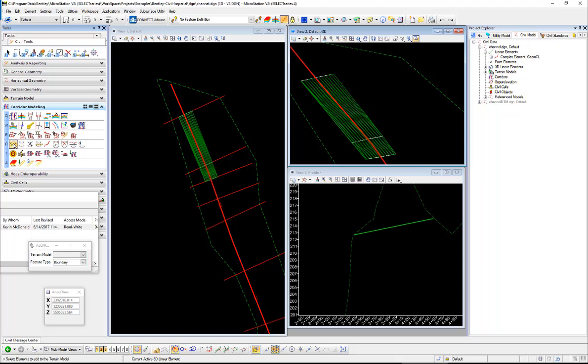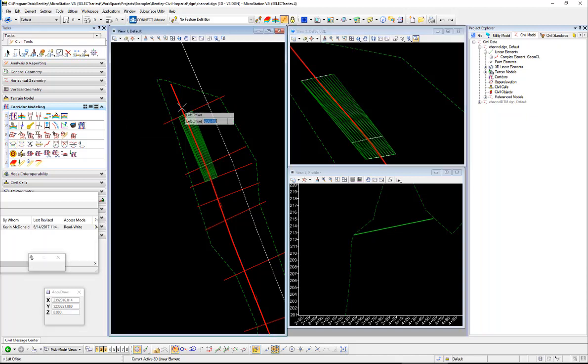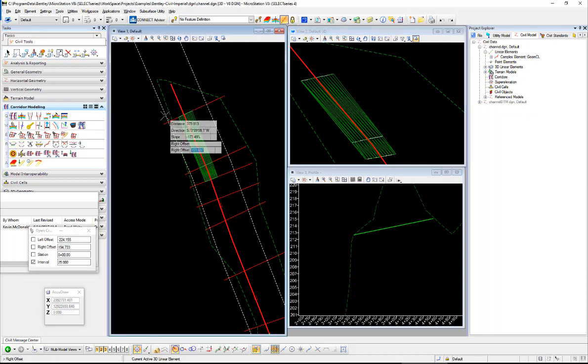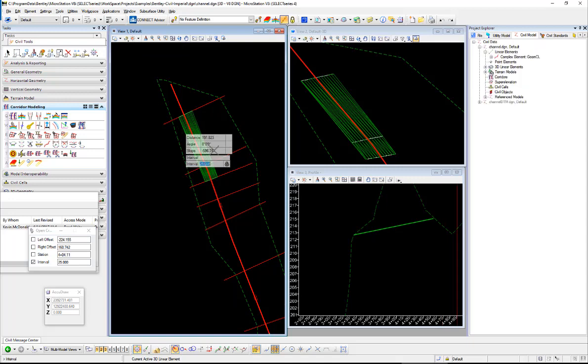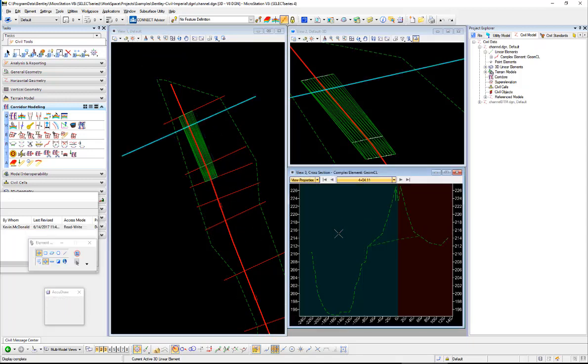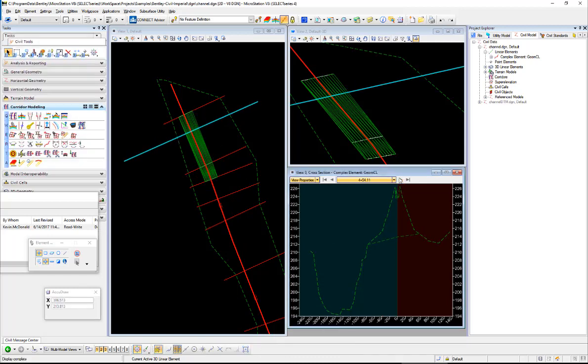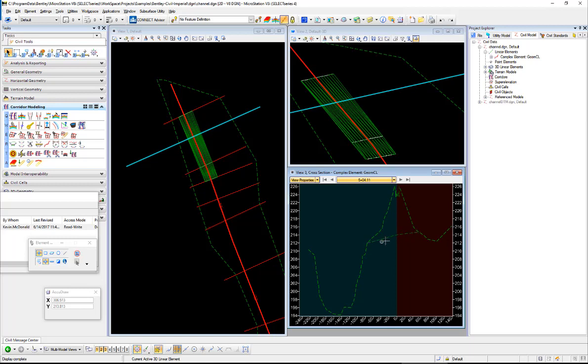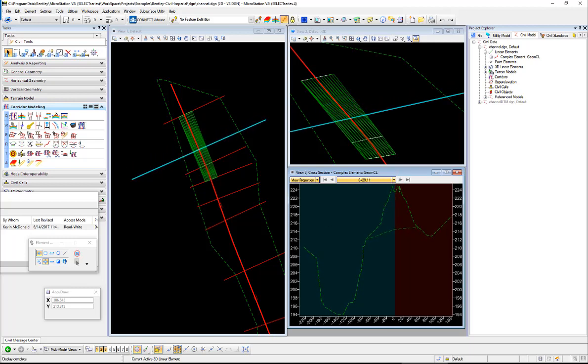And then just to show that it sees it now as a good 3D model, I'm going to cut some dynamic sections in that area. And as soon as I open my cross-section view down here, in this little view, I can see the terrain that it created is showing in my cross-section view, and that was the terrain created by just those three elements there.